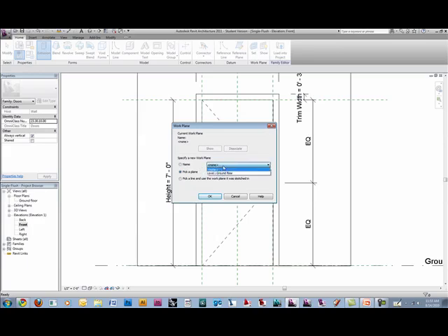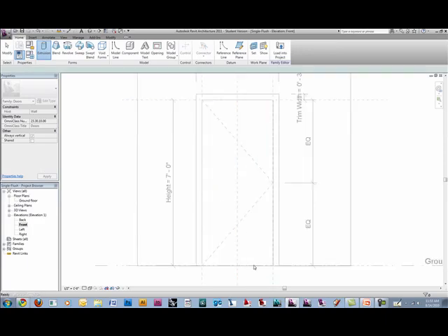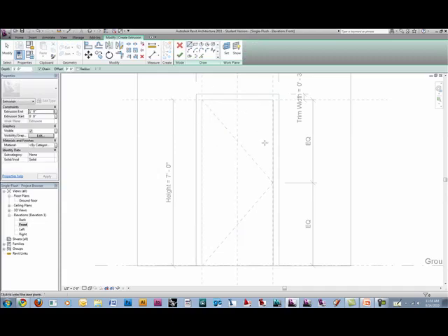And it's going to ask me to pick a plane, which for some reason it doesn't have a plane on there. Weird. This is where reference planes come in really handy, because if you have reference planes you can just tell it to be those. But obviously this normal everyday out of the box component from Revit doesn't have a front back plane. So we're going to pick one. If you pick one, all you need to do is pick geometry that you're drawing on, pretty much. So here's the door. I can click this geometry and now it'll let me draw straight on the door. I could also pick the trim too, it wouldn't matter, or pick the wall, anything that's flat.